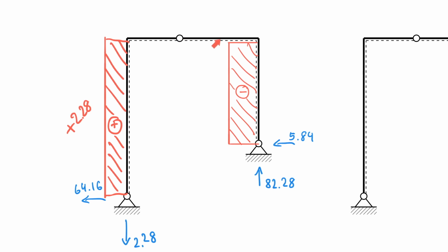So in fact, let's start to look at this. Now we need forces that push along the axis of this member. I guess the easier one to start with is using the force down here. If I were to make a cut here at the system up here, you can include all this and bring your internal forces here. But what you would find is that your normal force is only affected by the 5.84. And so that doesn't change anywhere to here, and it also doesn't change anywhere here, because remember, you only had a distributed force up here and nothing else. So the normal force diagram is almost done now.